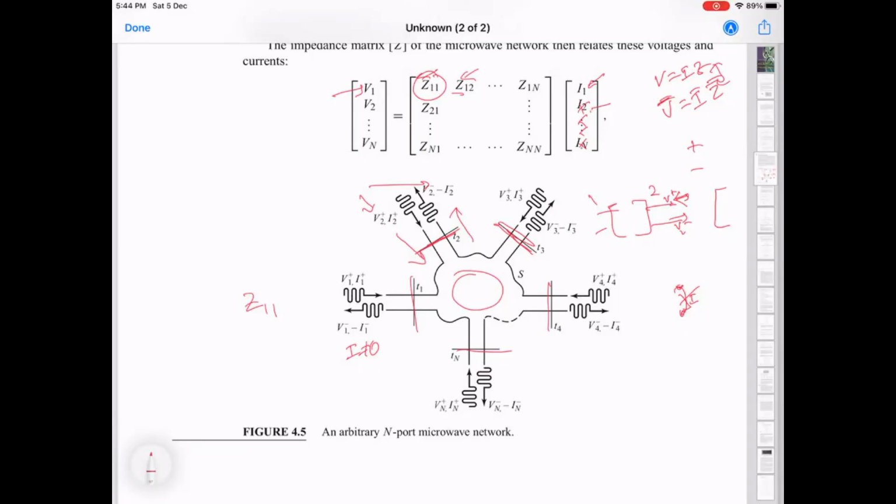So invariably, this is an exercise one never really does, trying to find the impedance matrix by using this procedure. Yet it's useful to consider because it has a meaning in terms of how you have defined the network and how the currents and voltages at each particular point are connected.